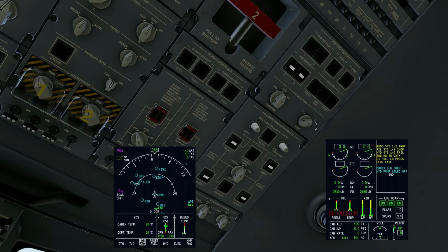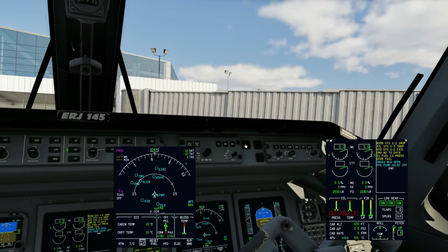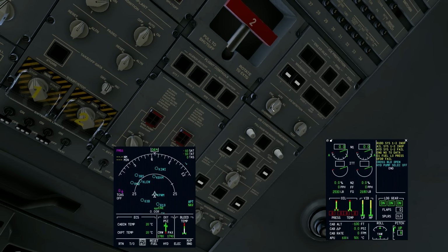And we're making sure that the system logic exists, it works and it woke itself up. We want to make sure that the messages are basically saying, hey, you've tricked me, so I don't like that. I'm not detecting ice, and that's a good thing. Ice detection 2 fail, I'm not detecting ice on system 2. That's actually a good thing. So that's a test we do on the ground, we do that first flight of the day, and that just checks the system out, making sure it's working electrically.